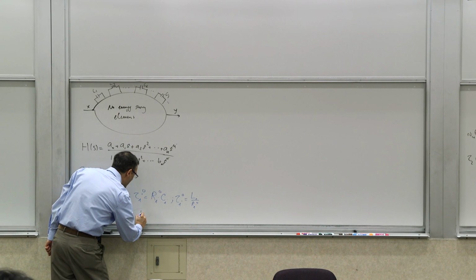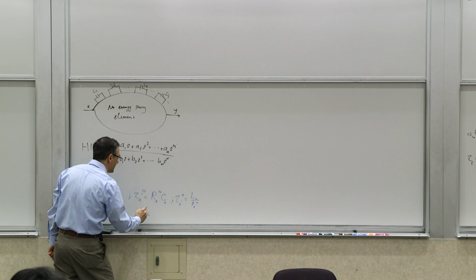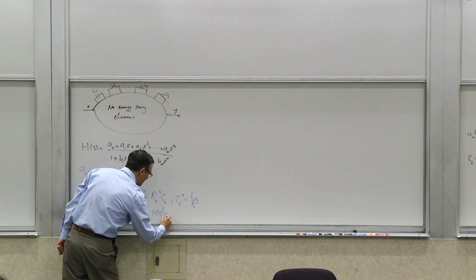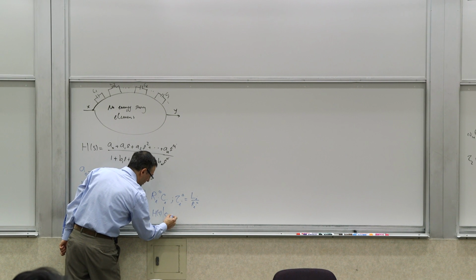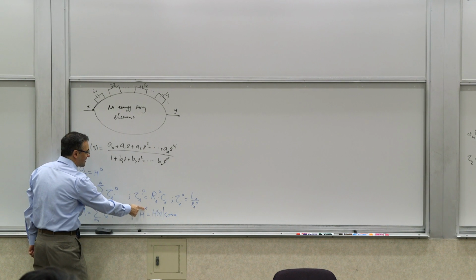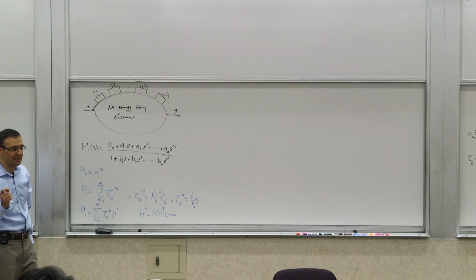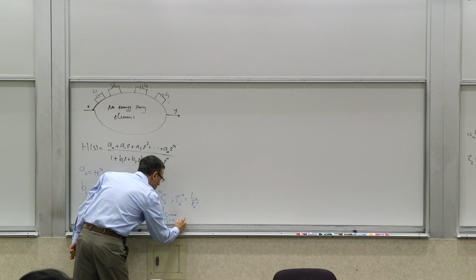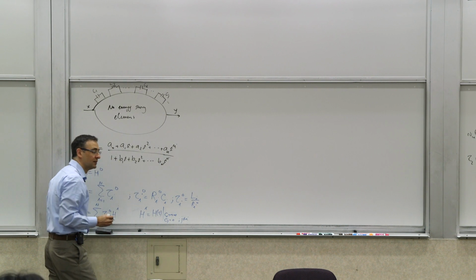So what is hi? hi was the transfer constant, meaning it was the transfer function when the element i, in general a capacitor or inductor, is infinite valued, and we know the rule is that anything that's in the superscript is the index of the element that's infinite valued. I've said this several times. And all the other Cj's are 0 for j not equal to i.